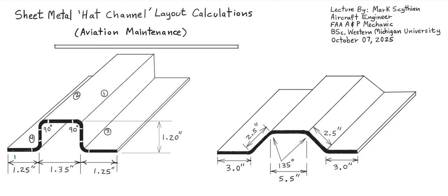So the calculations part is as follows. We have to first label our components: flat 1 plus bend allowance 1 plus flat 2 plus bend allowance 2 plus flat 3 plus bend allowance 3 plus flat 4 plus bend allowance 4, and then finally flat 5. So we'll call the working lengths, including the projection of the bend on the vertical and horizontal axes, the mold length line, the finished.